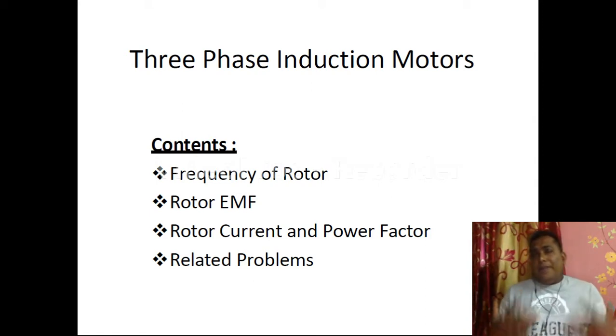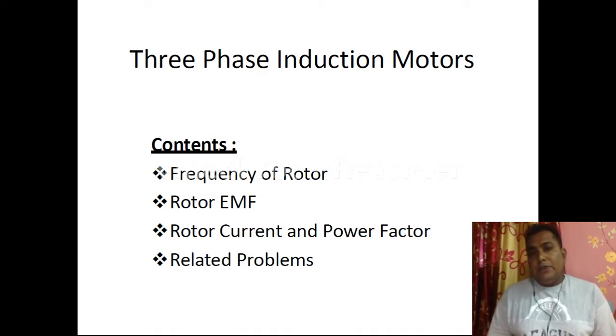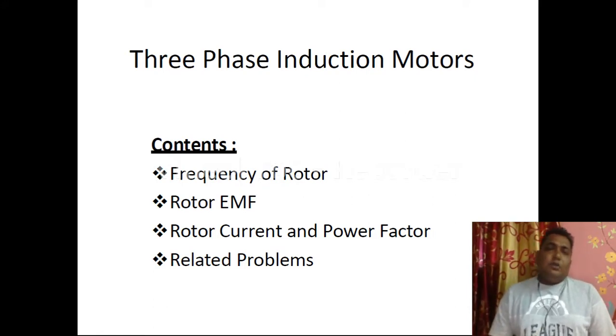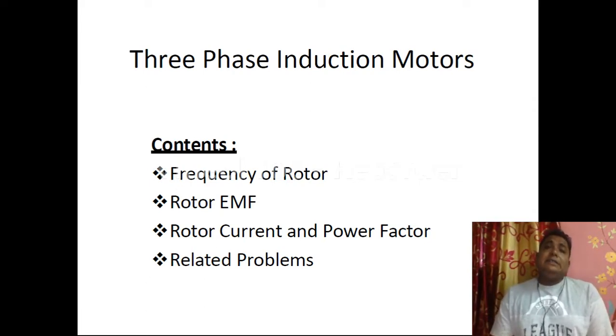Due to the rotating magnetic field, there is flux cutting in the rotor bars and EMF generation, due to which a torque is generated and the rotor rotates. So some EMF is induced in the rotor, with some EMF value and some frequency value, which differs from the stator section. The frequency we give as input does not remain constant on the rotor side, because there is a relative speed between the synchronous speed, the speed of the flux, and the speed of the rotor.